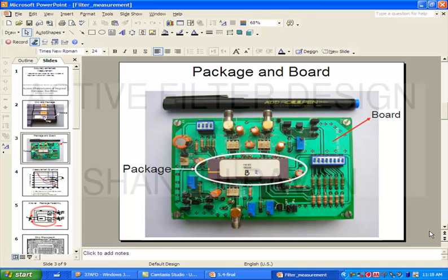And as I have discussed before, all these paths are differential paths. So the input signal going in must be a differential signal, and this must be riding over a common mode voltage, right. But unfortunately most test equipment you can buy today is single ended, right. So the actual sine wave that you get from a signal source is with reference to ground. You will not get two sine waves which are 180 degrees out of phase riding over a common mode. It is your job to take the single ended voltage and convert it into a differential one. So how will you convert from single ended to differential riding over a common mode? There are many ways of doing it.